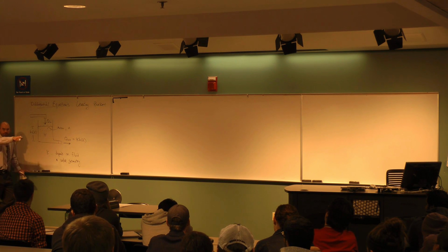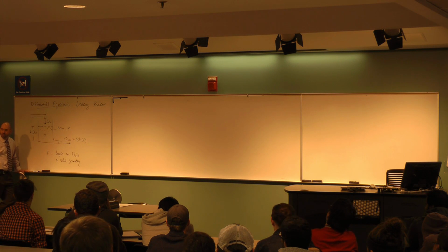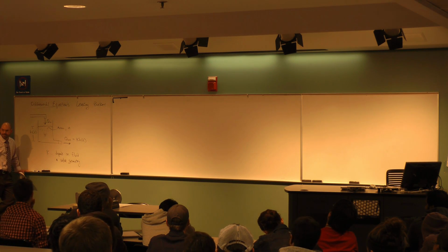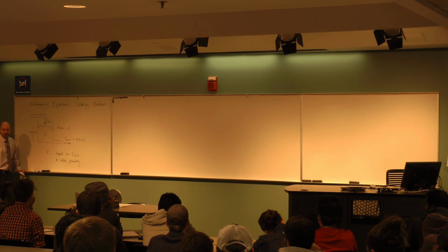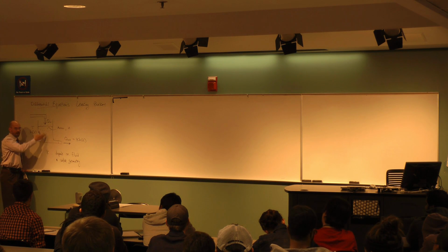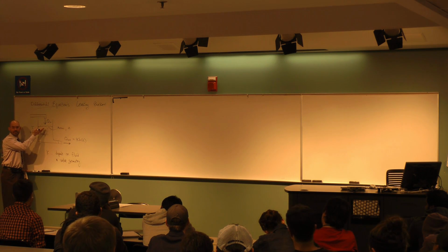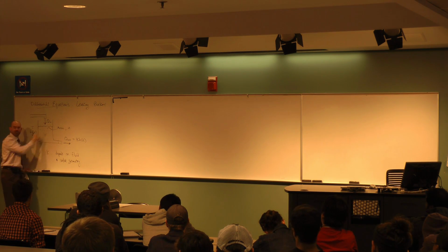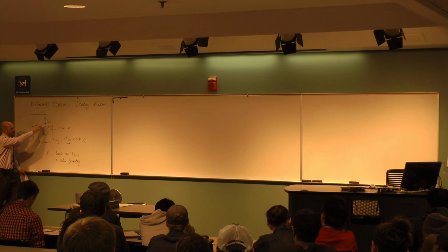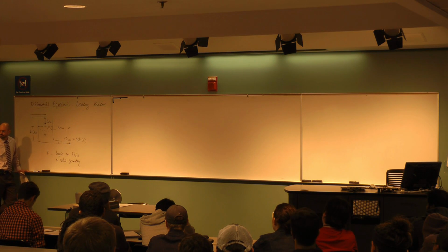When Q in and Q out are the same. Sure. When Q in and Q out are the same. So the statement is, there's going to be some portion of time where Q in and Q out are not the same. That's when I'm adding volume to the tank. But then at some point, I build up enough pressure in here that the Q out balances the Q in, and the liquid will stay at a steady state.